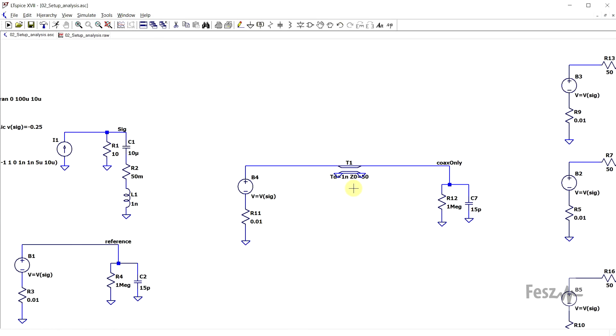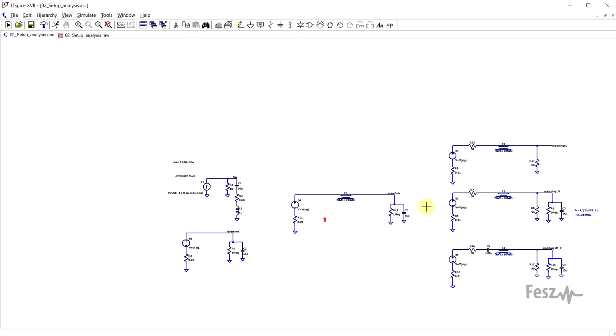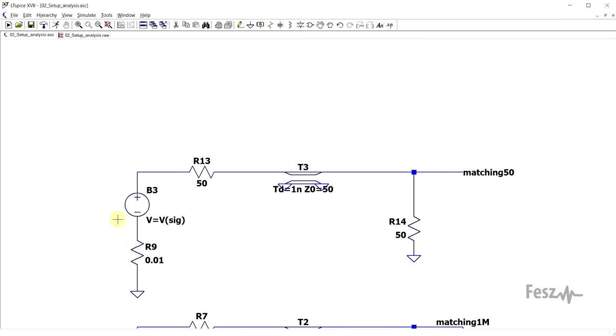So the easy way to fix this is to create a matched impedance system. This means having a 50 ohm signal source. This can be done by adding in a 50 ohm resistor with our signal source. Then this is matched to the 50 ohm transmission line. And we also need 50 ohms at the other end. So for example, if the oscilloscope has a built-in 50 ohm termination.